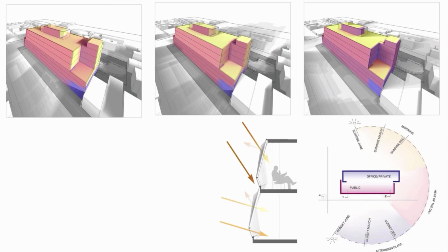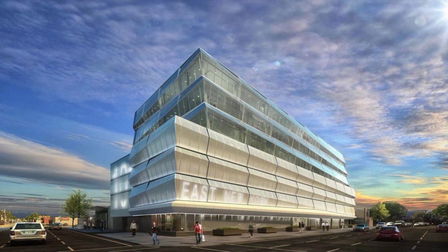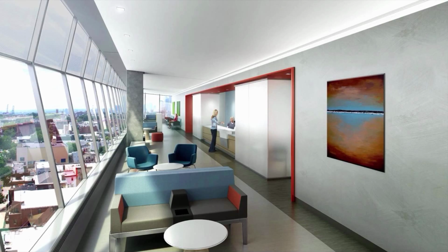So we're doing some initial analysis in FormIt and simultaneously doing that in Revit, starting to understand the geometry of the exterior wall of this building and how that affects solar gain, so you're not just relying on the glass of the building, which I'll touch on in a minute. There's a rendering of that building which shows the three-dimensional nature of that wall, how it's used to basically shade itself. And what you can see here is a view of the interior space.